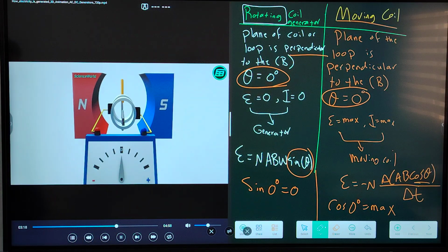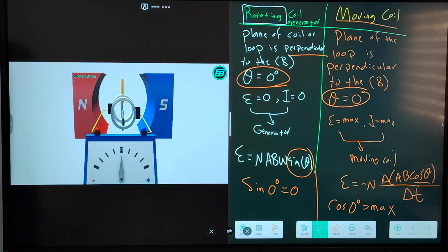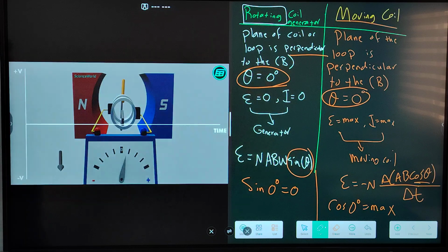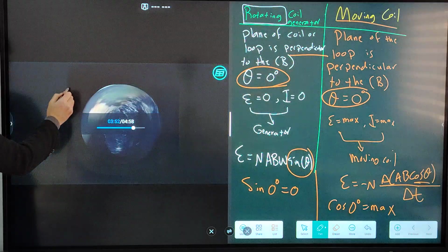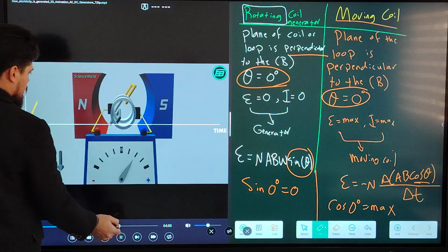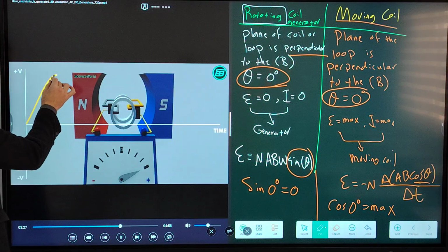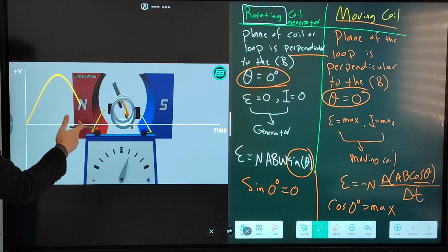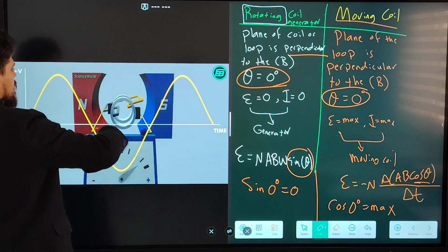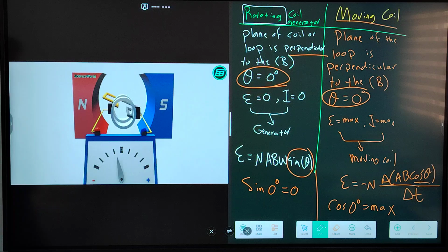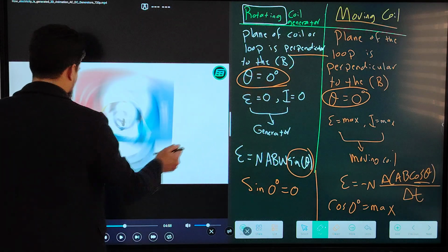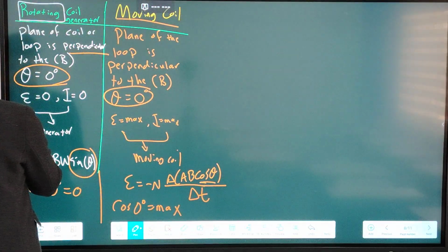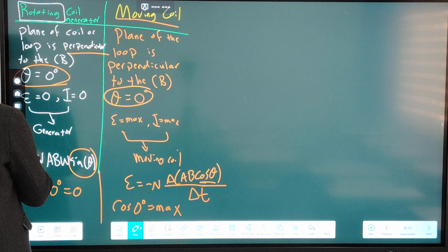Between half and complete cycle, Fleming's right-hand rule indicates that the direction of current is outward. After each half cycle, the direction of the current changes. In an AC generator, at the three-quarter cycle, the electric current reaches a maximum. As the plane becomes perpendicular, it becomes zero and continues. After every half cycle, the direction of the current changes continuously. So that is why in an AC generator, both magnitude and direction change continuously. I hope you benefited from this video about the AC generator.